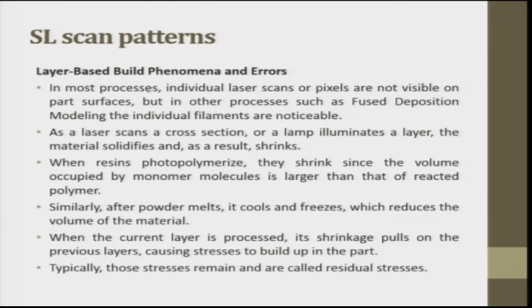In most processes, individual laser scans or pixels are not visible on the part surface, but in other processes such as fused deposition modeling, the individual filaments are noticeable. In SL it is not there. As the laser scans a cross section or a lamp illuminates a layer, the material solidifies and as a result shrinks. So, in SL, shrinkage is one big phenomenon which has to be taken care of.